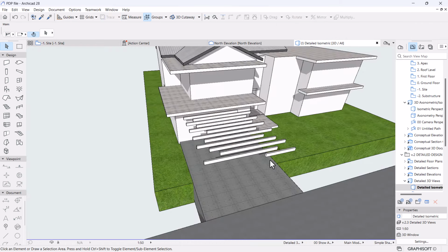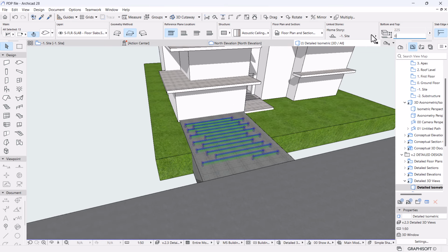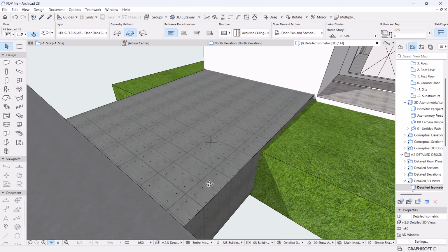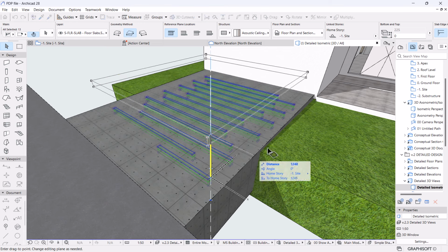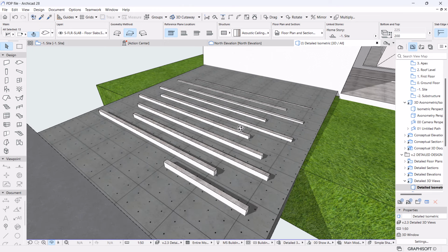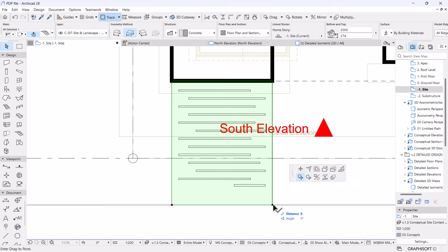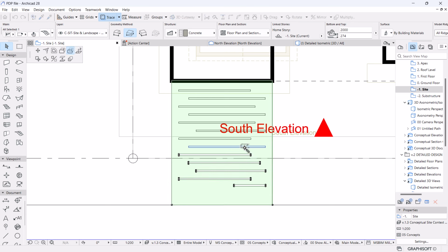Yes, if we check on 3D, you'll have that group there. Let's have it at 0. Let me see it from here. Okay, we could use subtract solid element operation to subtract this from our mesh, but also we can use the actual subtract polygon, which is this. I'll pick one of the points, then activate subtract with polygon, and activate the magic wand tool by pressing and holding the space bar. Then I'll click on each strip or element like that.